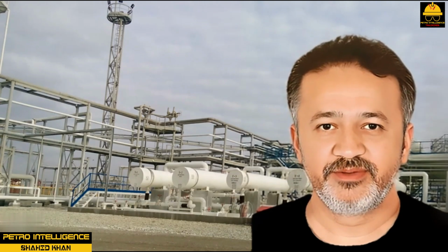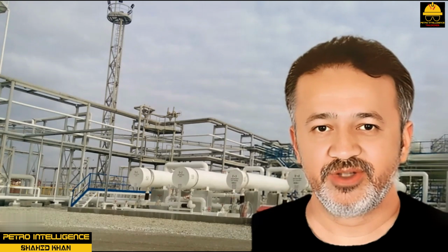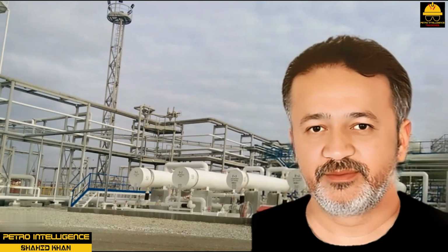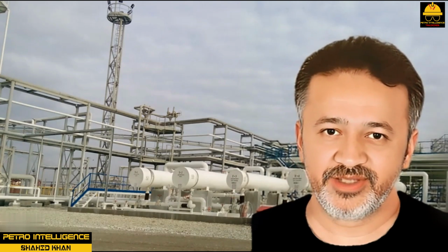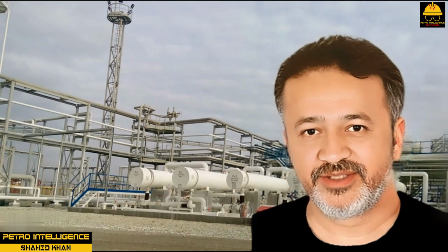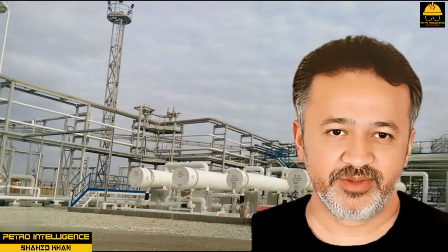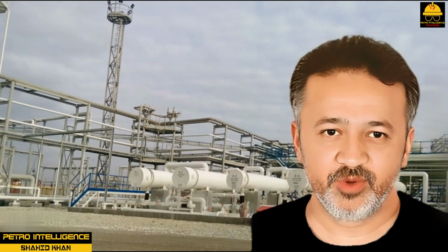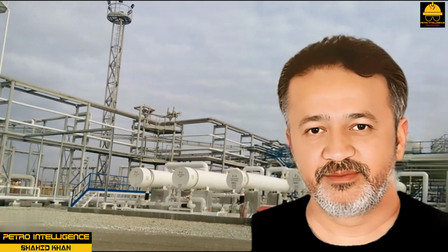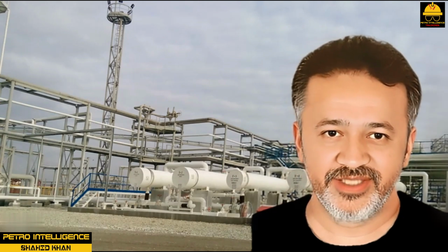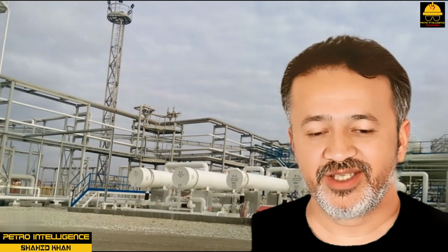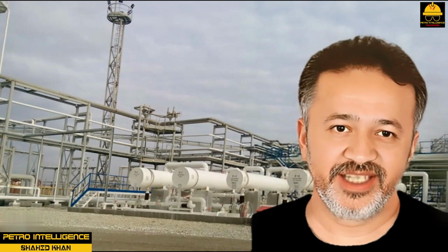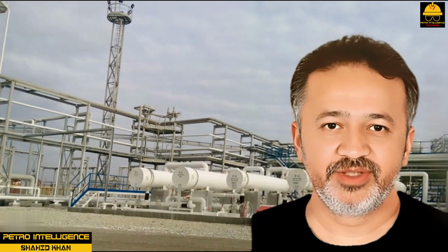Air-cooled heat exchangers have none of the problems associated with water such as fouling or corrosion. They are simple to construct and cheaper to maintain than water-cooled exchangers. They have low operating costs and superior high-temperature removal above 200 degrees Fahrenheit or 93.33 degrees Celsius. Their disadvantages are that they are limited to liquid or condensing service and have a high outlet fluid temperature and high initial cost of equipment. In addition, they are susceptible to fire or explosion in cases of loss of containment.